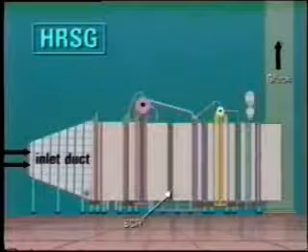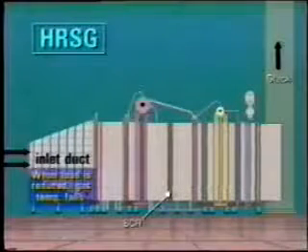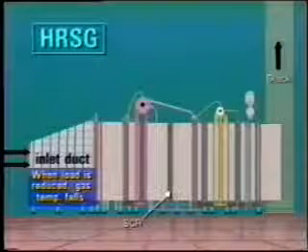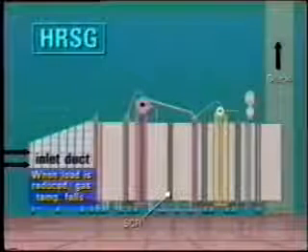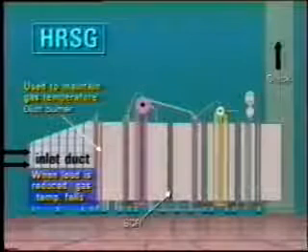For the SCR process to function correctly, it must take place within a very narrow band of temperature, and it is this which decides the location of the converter. This temperature consideration introduces a problem when the gas turbine load is reduced and the gas temperature subsequently falls. The use of fired burners to maintain gas temperature helps overcome this problem.